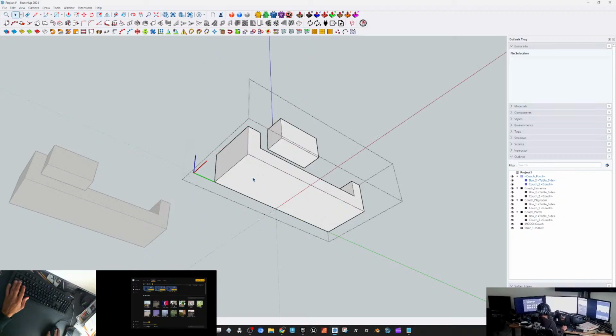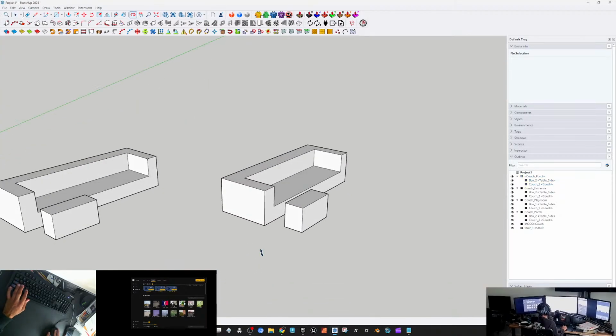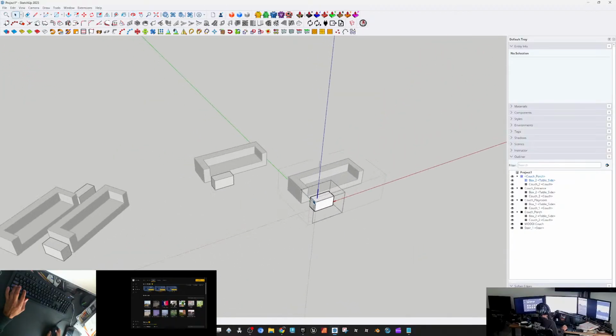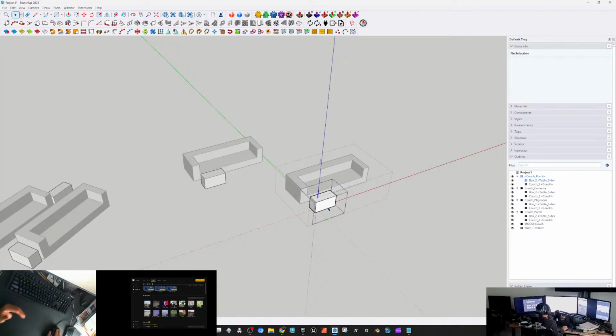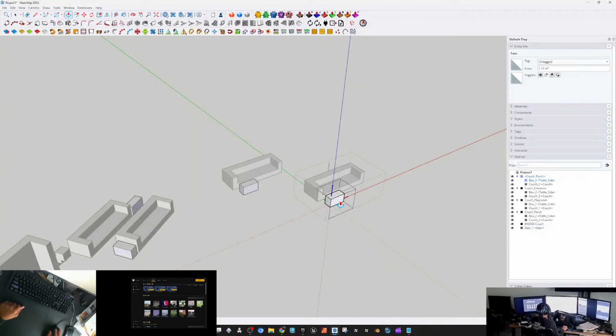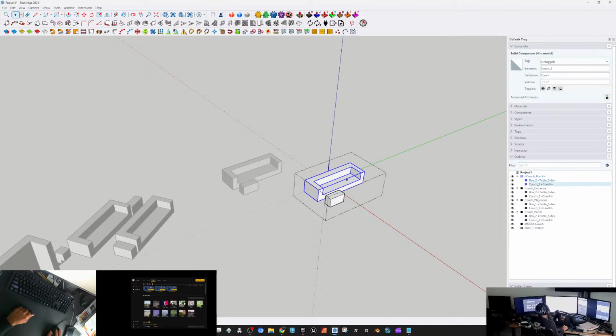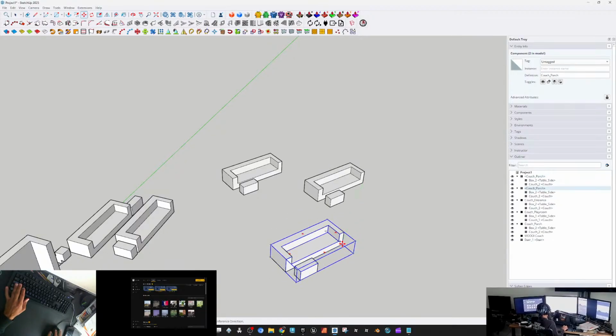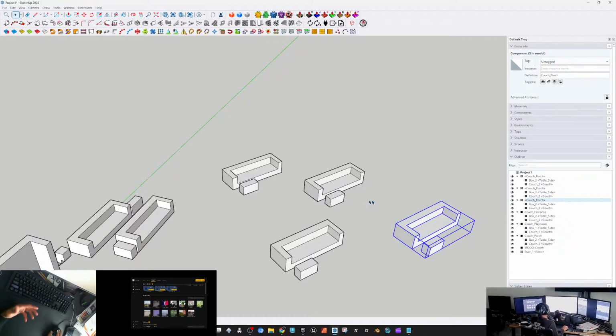And now my axis is updated. I'm gonna hit yes, we want those changes to be made. If I click into this component, now you can see that even still what lies within this component is a component. So I'm not sure exactly how this translates inside of Unreal Engine, but this is now a component in SketchUp that allows me to then make modifications to, let's say I move this couch around and I duplicate it in the scene because I want 3 configurations of this.